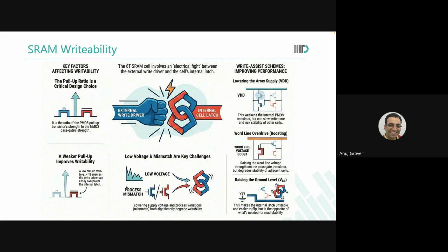So, that was also the reason why we estimated Vx before we estimated the Vint, or how much I am able to discharge the one node during the write operation. This was a question one of you asked. Because I need Vx for density purposes, and for memory cells, area is diamond. So we calculated Vx first, then we came to Vint. Is that okay?